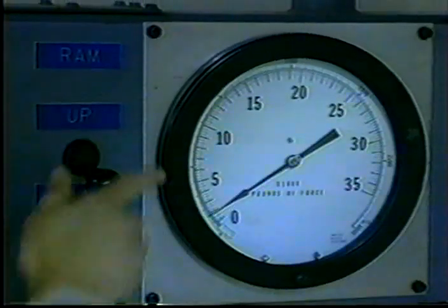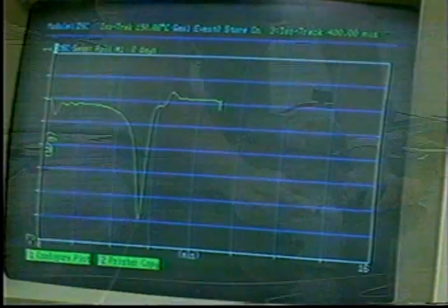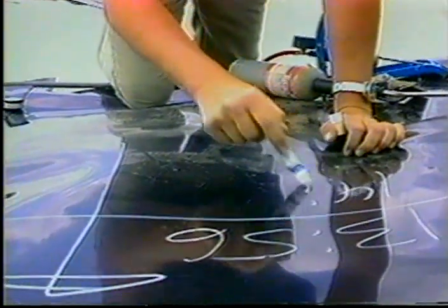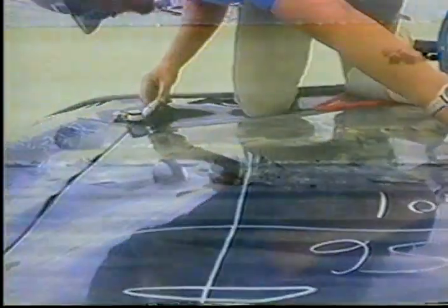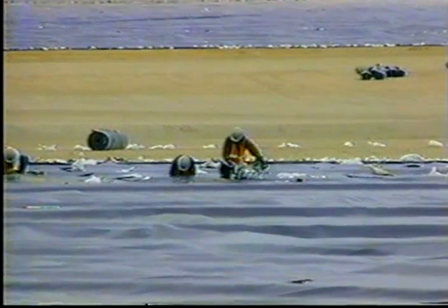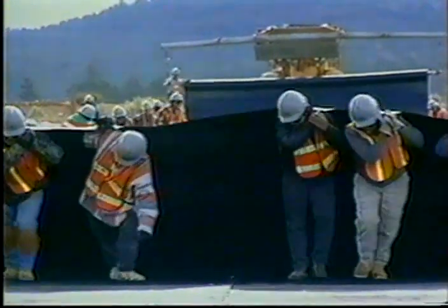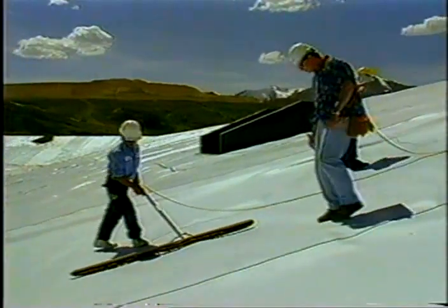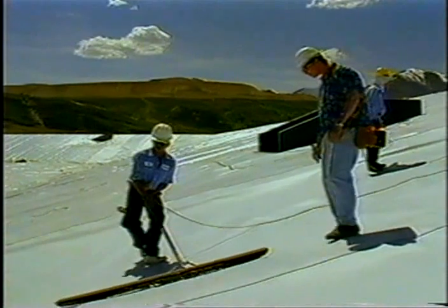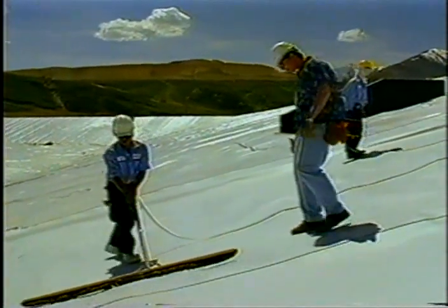QA starts with conformance testing of the delivered materials to make sure they meet the specifications. Construction quality assurance, CQA, is also essential in the field. All the testing in the world is of little effect if the geosynthetic materials are damaged during installation. Translating a well-tested design into an efficient facility depends on good site management, competent workmanship, and the full-time presence of a quality assurance team.